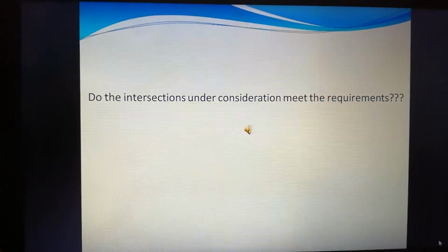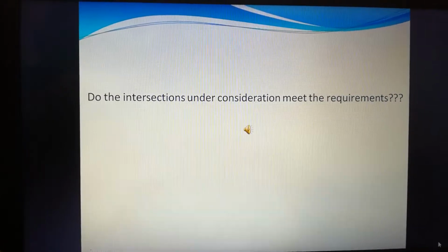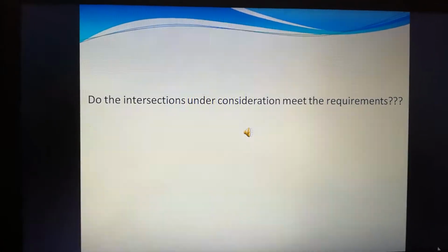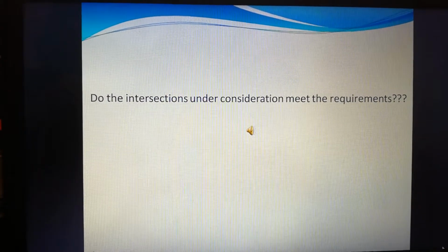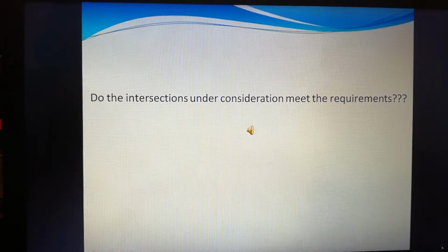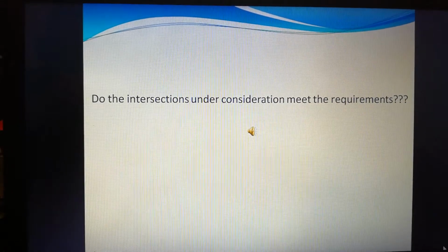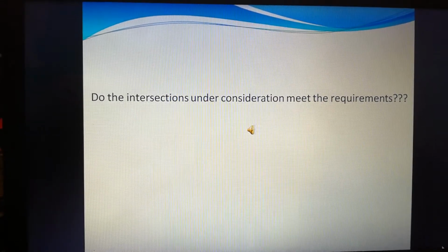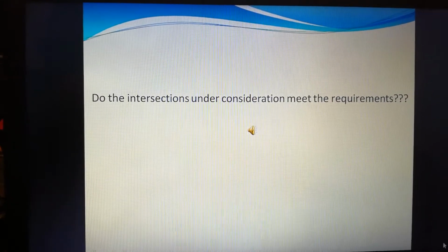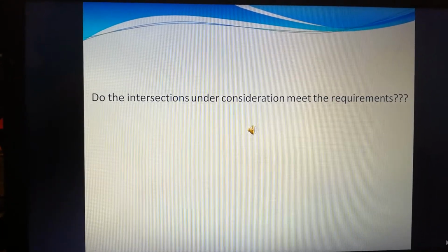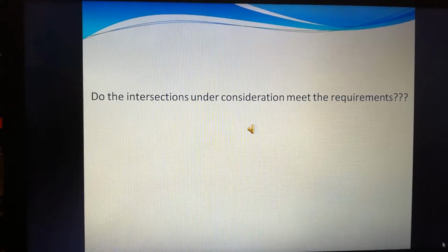Furthermore, the complexity of the intersections reduces the visibility of the road users, especially cyclists, because there are only few of them on the road. Therefore, motorists tend to forget, in inverted commas, about them. The crossing distance is long due to the size of the intersections. This exposes cyclists to conflicts with motorists as they have to take longer to go through the intersections.